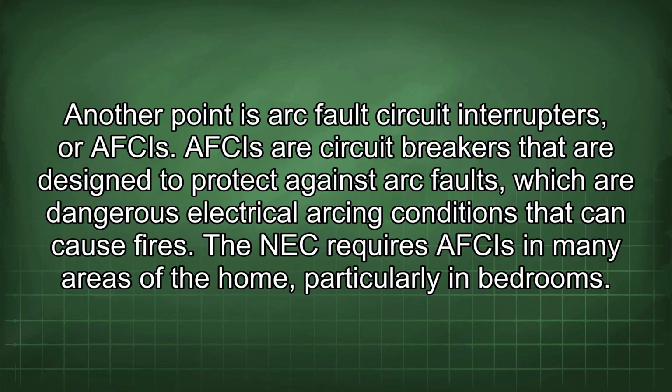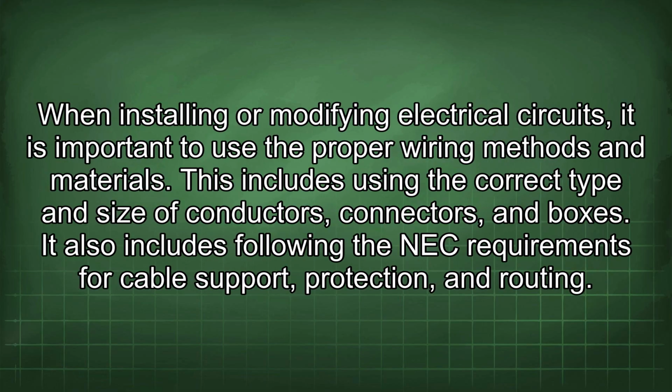Another point is arc fault circuit interrupters, or AFCIs. AFCIs are circuit breakers that are designed to protect against arc faults, which are dangerous electrical arcing conditions that can cause fires. The NEC requires AFCIs in many areas of the home, particularly in bedrooms. When installing or modifying electrical circuits, it is important to use the proper wiring methods and materials. This includes using the correct type and size of conductors, connectors, and boxes. It also includes following the NEC requirements for cable support, protection, and routing.